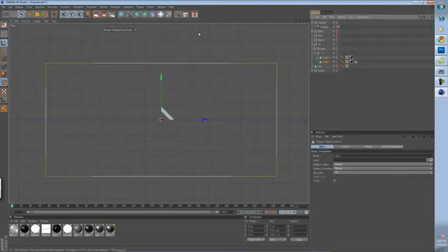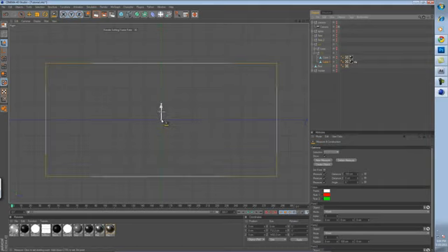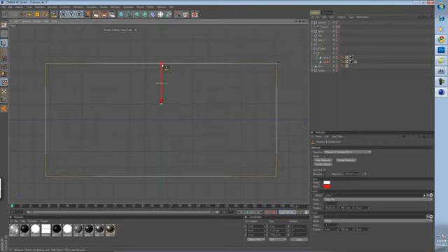So I have my cube isolated now, and to find out its measurements, first there's a given. I know that the y-axis divides it perfectly into two parts, and so does the z-axis, if you can see here. I know that for a fact, and so I can go under Functions, Measure and Construction, and it's going to take me from the origin up. So if I go anywhere near the edge, it's going to snap to the point, and then it's going to give me the measurement.